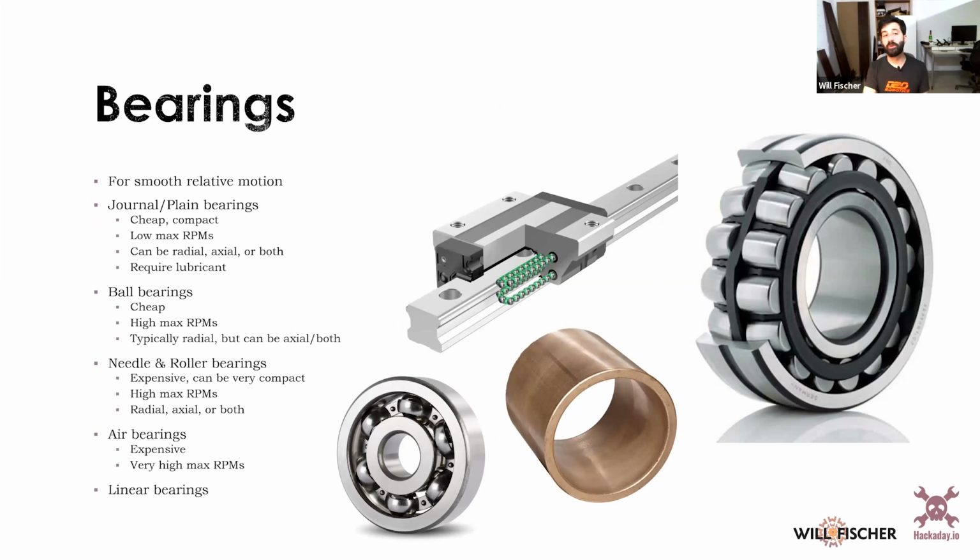Bearings are a really, really important part of rotational and linear movement because they allow you to constrain your motion in your degrees of freedom on some axes. So this is a plain bearing. You can see it right up here, and I've got a picture of it there. That allows rotation and translation along my shaft, and that's nice if I want to constrain things to move in a specific way.